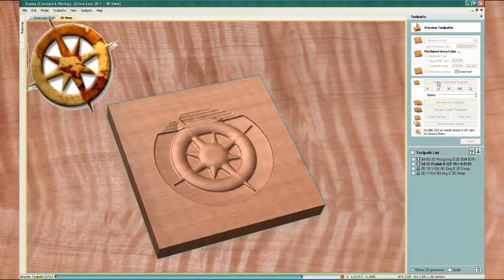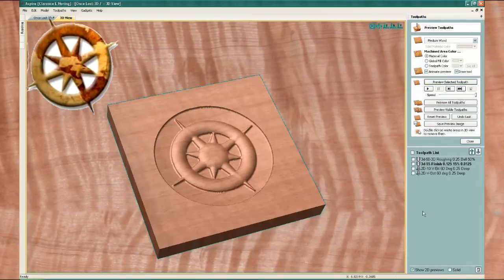Basically this design is in a bowl. It's designed to carve. I tried to design it so that the top edge of the 3D image is very close to the surface of the uncut board. Now, if you look down here where my mouse is, when I run over the 3D image, you'll see the Z coordinates. See right here, it looks like 0.006 deep, which is very shallow.